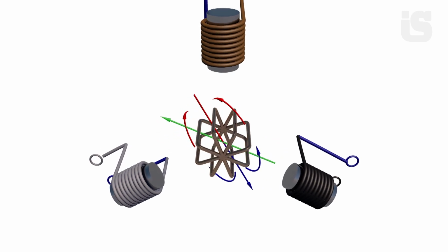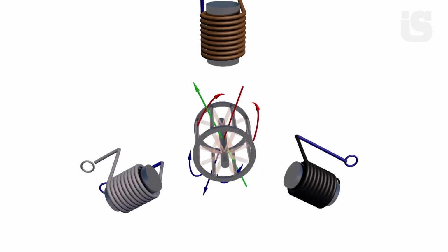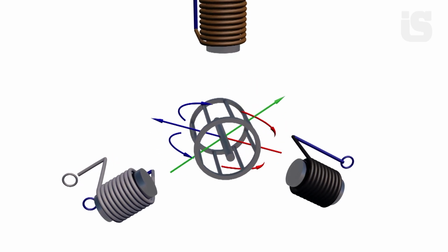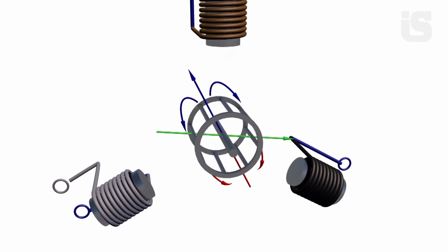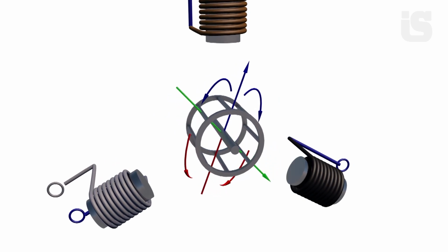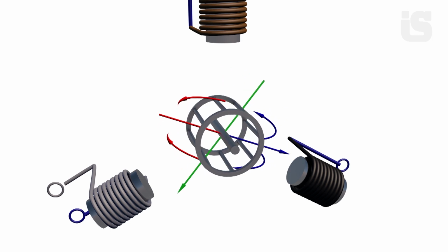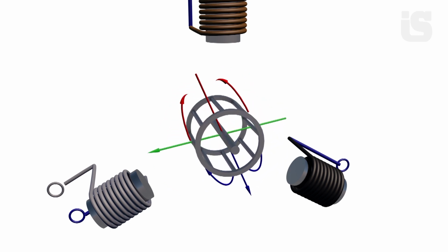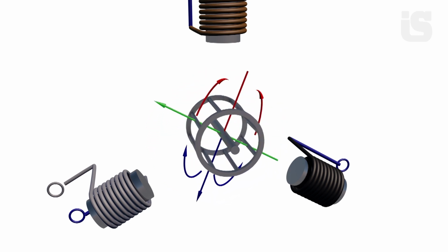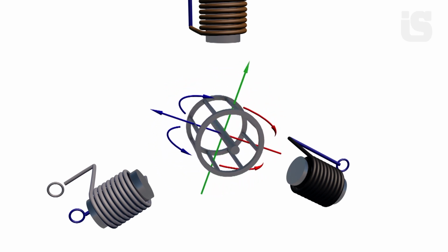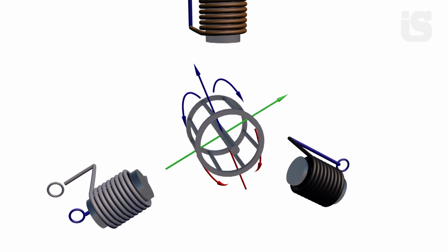In this electric motor, these frames are combined into a single structure. It consists of many individual bars. All of them are tightly connected at their ends by two short-circuit rings. The result is a single, solid structure resembling a cylindrical cage. Structurally, this is always a single closed system. Such a motor is called a Squirrel-Cage induction motor.